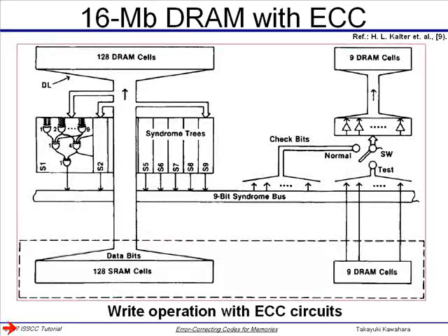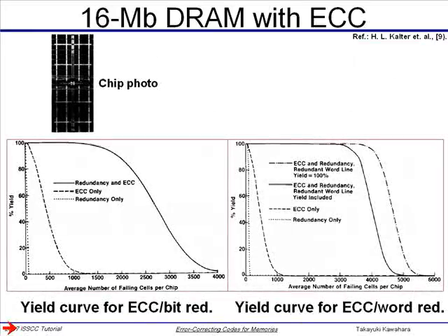Also, when writing, it creates the check bits, as I explained, and writes them down to the DRAM. In this work, another unique point is that he merged it with redundancy. So not only the ECC but also the redundancy. They have a very good advance in the yield curve. So that is another development of the ECC.